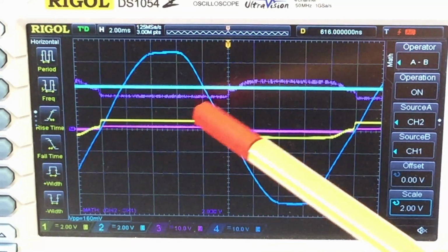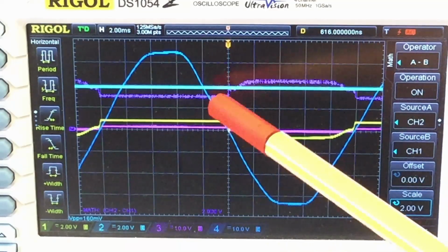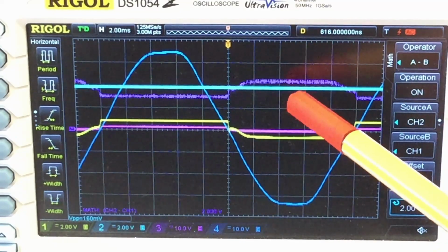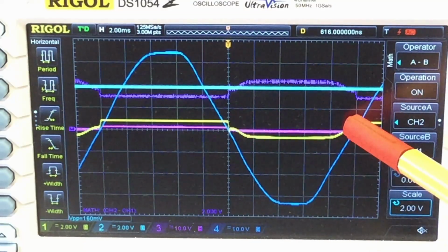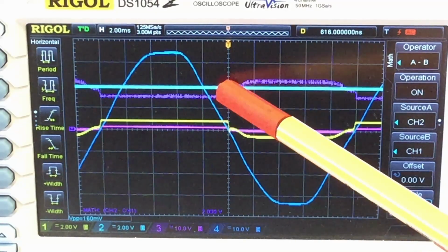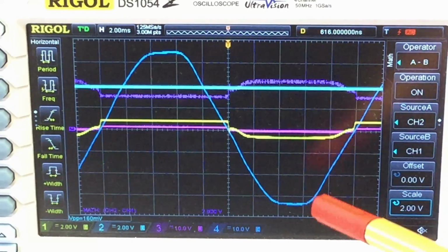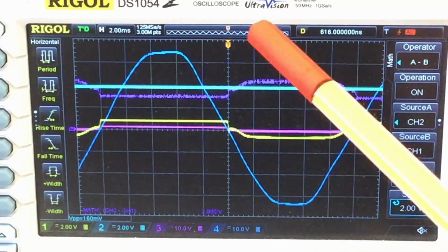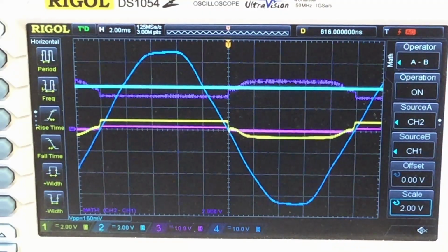And the gate current is actually fluctuating a little bit. So it's not a constant 7 milliamps, what we've seen on the multimeter, but since the voltage drop across the gate here drops a little, or goes even negative, the current through the gate is increased. Now that's all not very nice, and maybe there's a way around that.